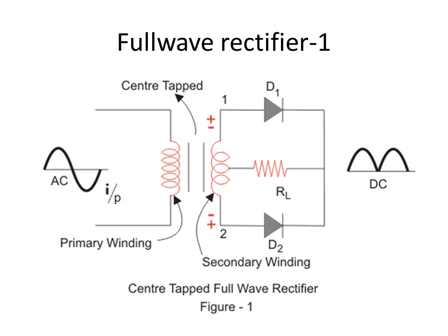But see, the other diode is reverse biased, and therefore it is cut off, so it cannot conduct current. So the current has got only one option, it can go through RL, and then it will reach the middle of the secondary of the winding. So that will complete one cycle. So during this time the current is flowing from right to left along RL.